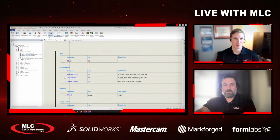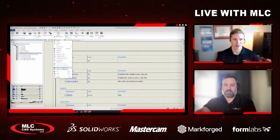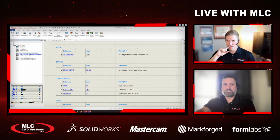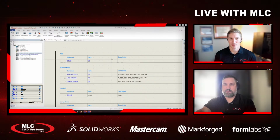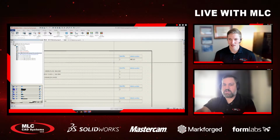So to do that, I can right click either right here or over on the report itself, and then we're going to choose this update report drawings. You're not going to delete them and regenerate or rebuild; it actually is regenerating them. It's going to just redraw them from scratch, essentially. So would it be the same as if you deleted them out of the tree and then regenerated? Same thing.